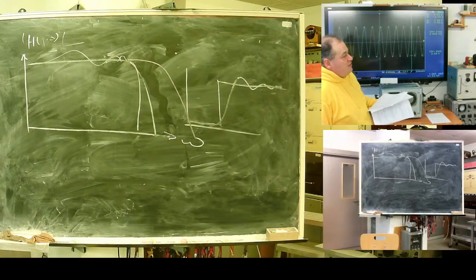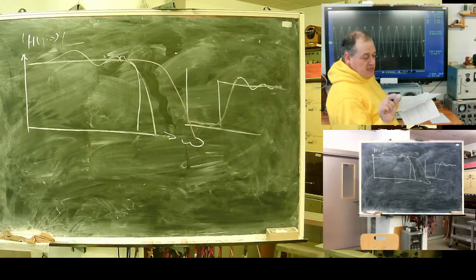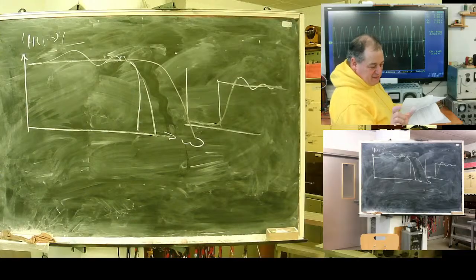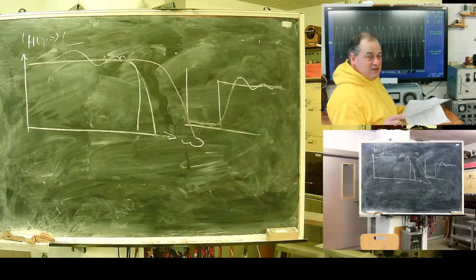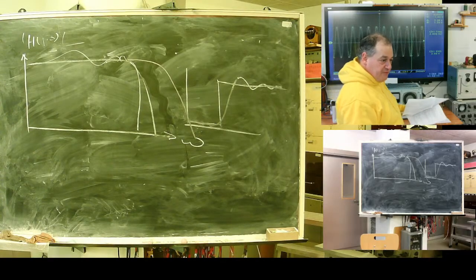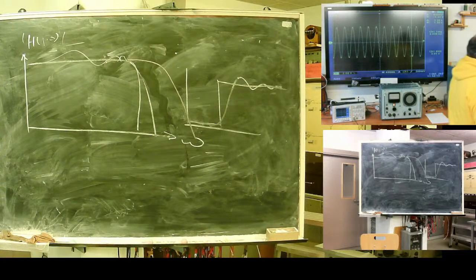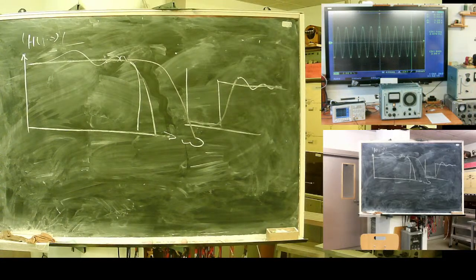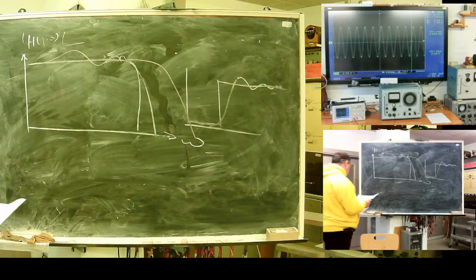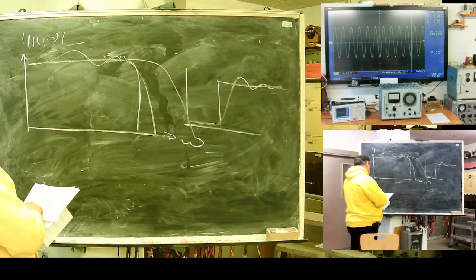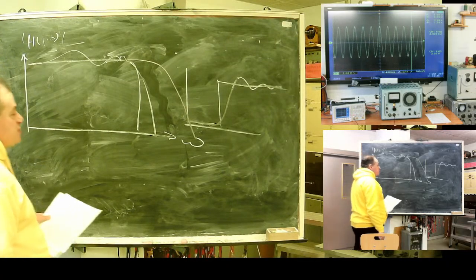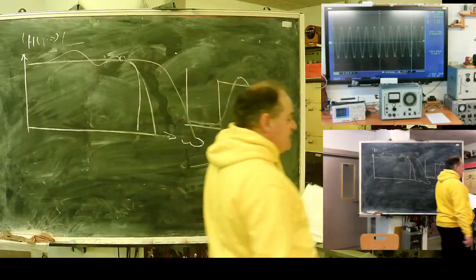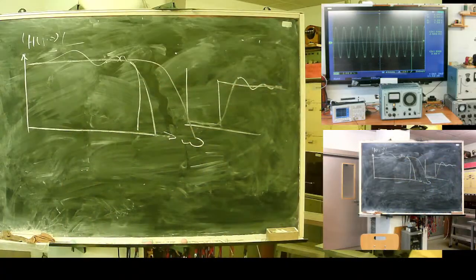If we deal with a narrow frequency range, for example 50 Hz plus minus 1, Chebyshev filter may be what we need, because it sharply cuts high frequencies. But if we need a wider range, Chebyshev maybe is not the best solution. Chebyshev filter on transients oscillates like hell.